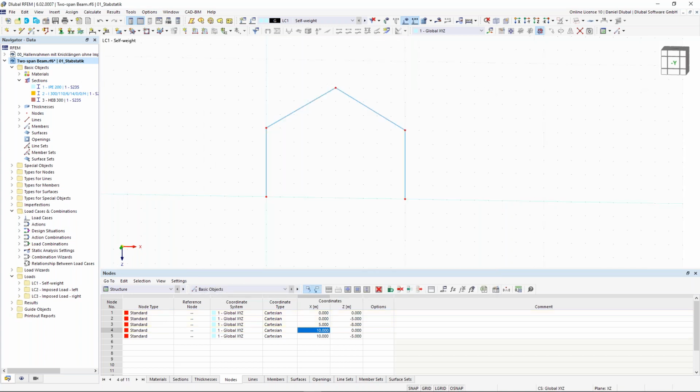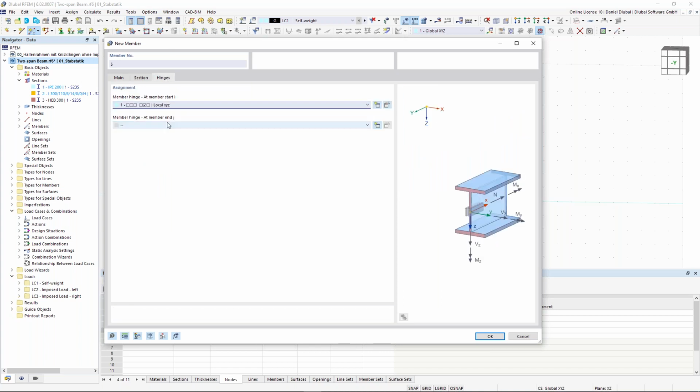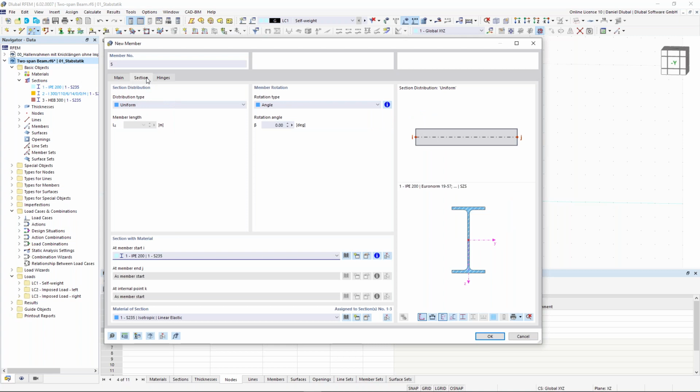Okay, the next thing is that we give it an additional rod. And now we have different member types. You can see here we have the member type beam, and this member type transfers all internal forces to other beams. I can add additional hinges to that beam. Let's do it in that way, and then I will explain other member types. So hinges, I say the phi y should be activated, so that we will have bending moment hinges.